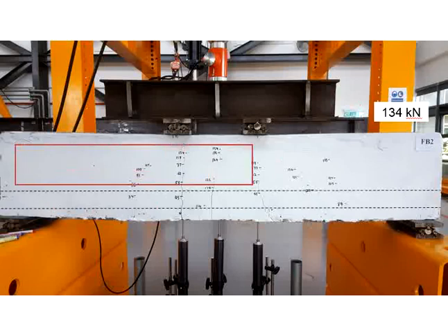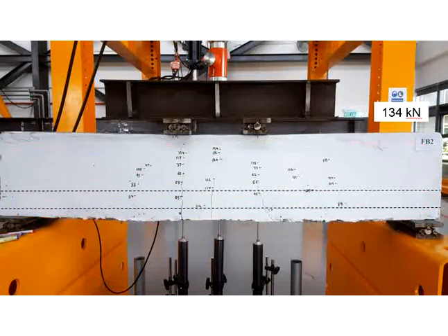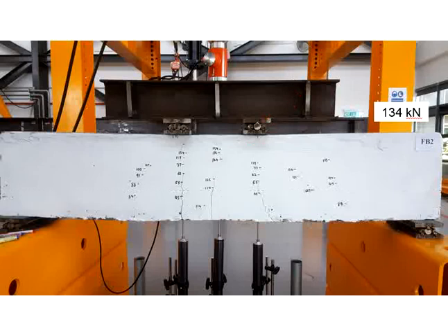Let's say now if you embed something in the beam specimen, the rate of propagation of the cracks may bring you some additional information regarding the response of the specimen. For example, if you have a void somewhere here, it is expectable that the crack will propagate faster in this region. Back to the point just now, normally I do not recommend tracing the crack lines because you can observe the crack width to give you some idea of the critical damage of the specimen.